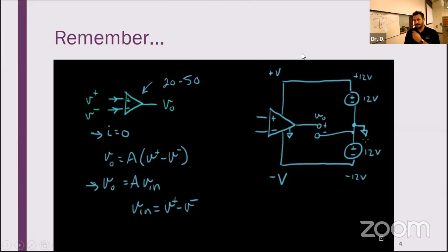And what we're going to do is assume that all of this stuff is always hooked up. And we're just going to use an even simpler symbol. Just the three terminals like that. And you'll know that all the rest of the power supply is hooked up that way. The thing to keep in mind is there's a large minus voltage, there's a large plus voltage, and the ground level, the ground node, is right in between. So positive voltage is high on the page, negative voltage is low on the page, and V out can go both positive and negative around ground. So that's your voltage framework to keep in your head.